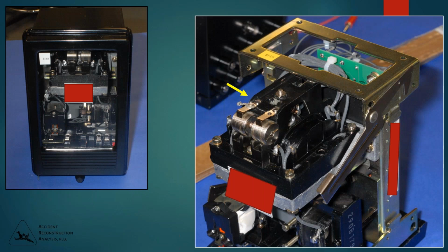So the next component is an under frequency relay. I've blacked out some of the manufacturer's identification, but a client sent this in to us. This had been recently installed and experienced a failure. The troubleshooting at the facility where this was used determined that there was a coil open on the induction cylinder, which is marked with a yellow arrow in the right image.